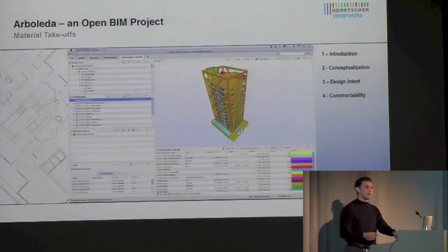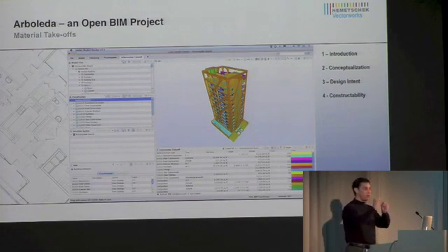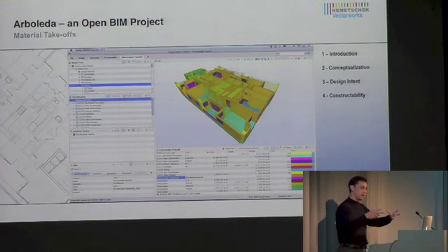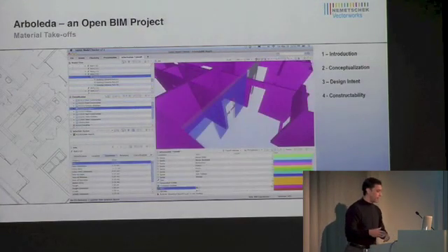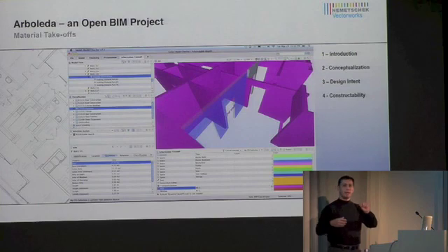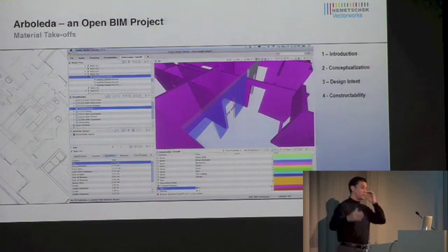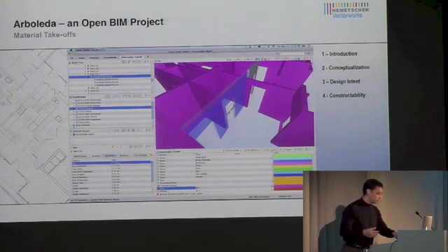Here's a sample inside Solibri Model Checker where you can color code each one of the objects, and Solibri will give you a report of all the pieces, not just from the entire building. It can also be just from a single typical apartment unit. And as deep as, hey, maybe I just need the square footage of one space without the doors, because I need to know the amount of paint that I require.